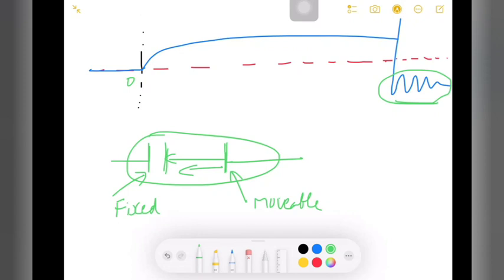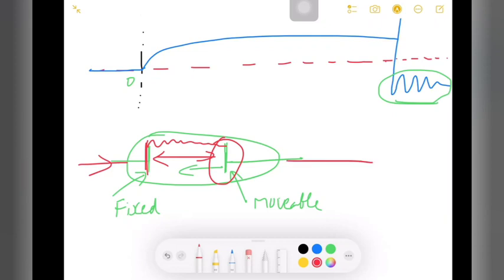Whenever the fault occurs, what happens? I need to bring back this electrode in such a way that I am maintaining a gap within the circuit breaker. When you try to move this movable electrode far from the fixed electrode, there will be a spark between the two electrodes because of the very high voltage. The current will be flowing from the circuit here. When you try to break the circuit, a very high amount of current will be flowing here.